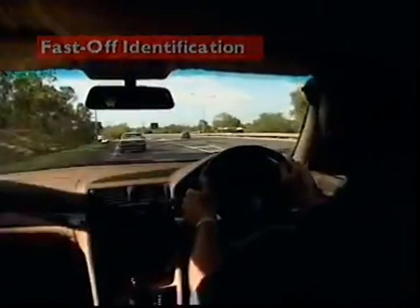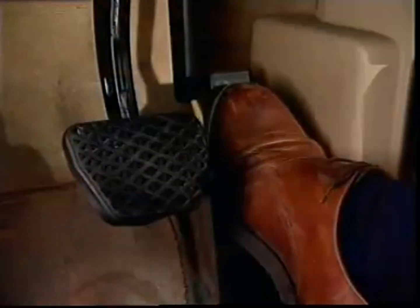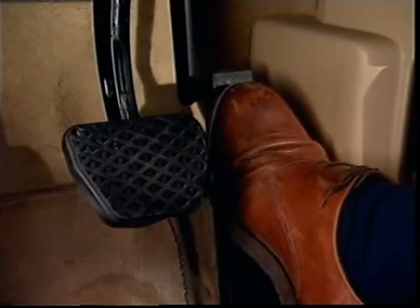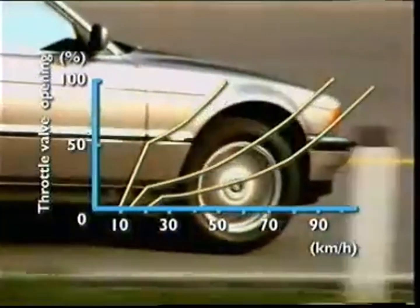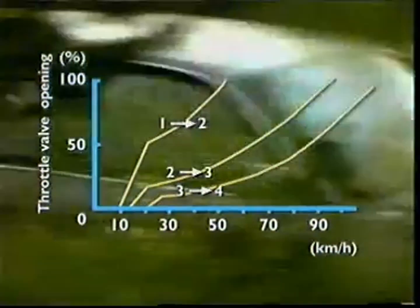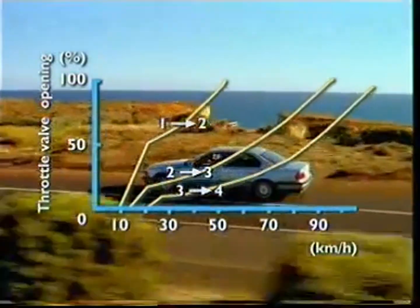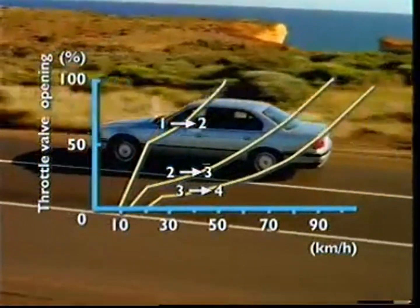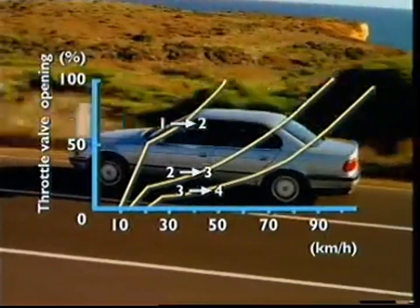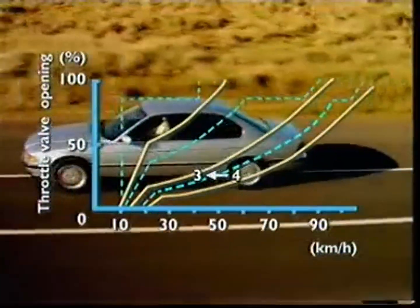In order to slow the vehicle, the driver lifts his or her foot off the accelerator and, if necessary, applies the brakes. In normal driving, closing the throttle prompts the transmission to upshift to a higher ratio if it is not already in top gear. In a higher gear, the engine contributes less to the braking process, and when the accelerator is depressed again, a downshift usually takes place.